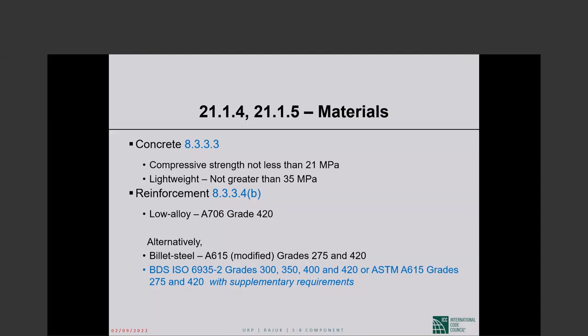an upper bound on the strength of normal weight concrete. Almost every other code tells you concrete cannot be any higher than so much in strength. ACI 318 does not believe in that kind of a higher limit. We have, over the editions, adjusted requirements where the properties of high strength concrete are different from those of normal strength concrete.